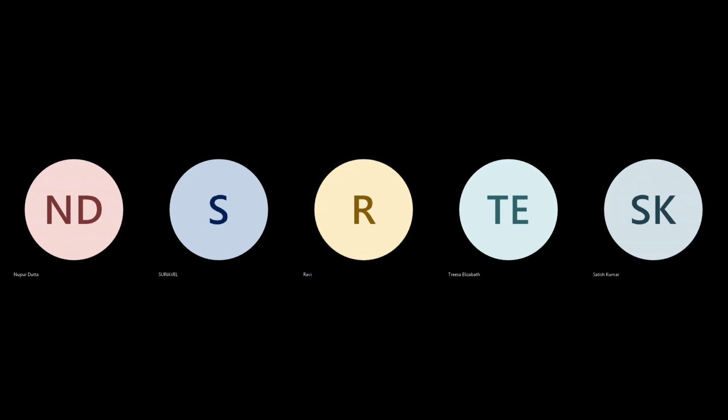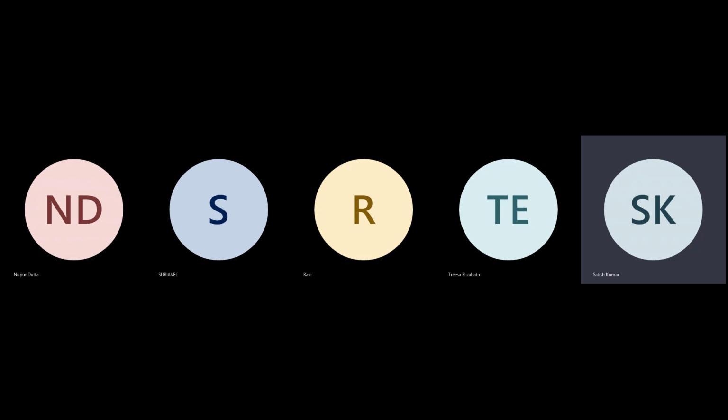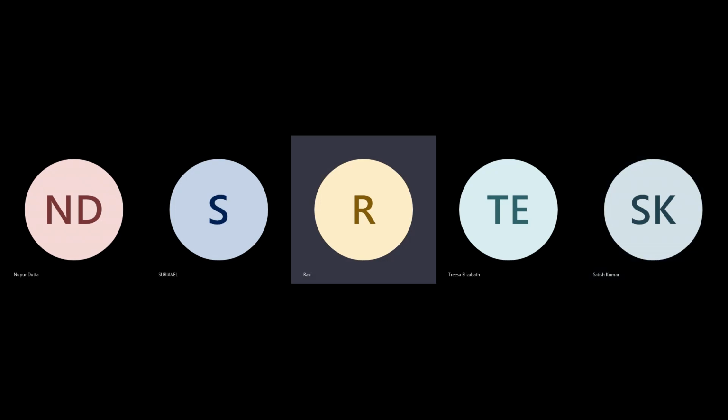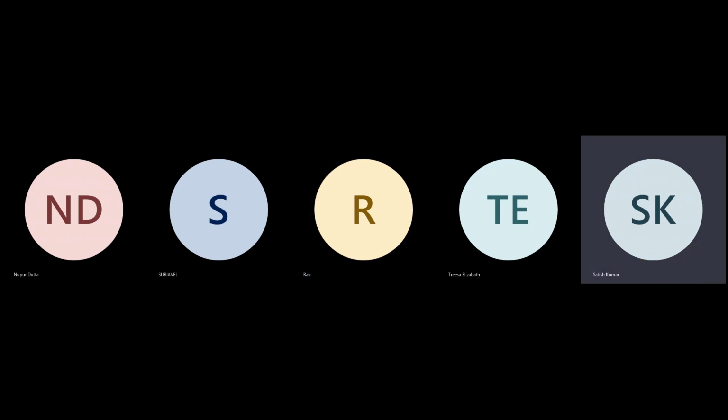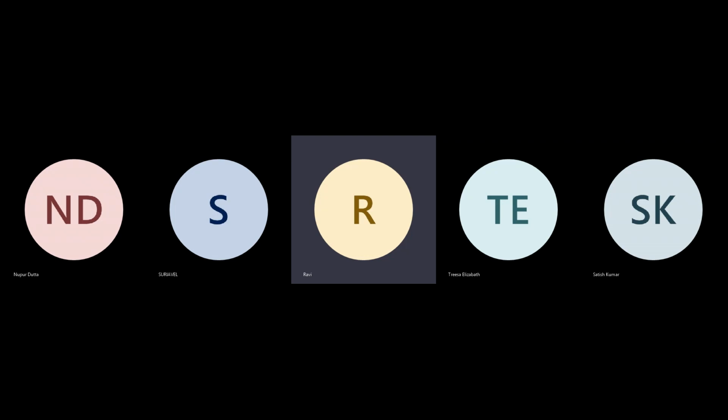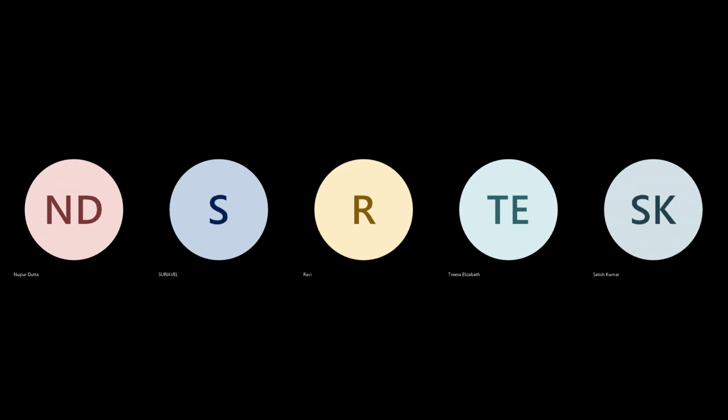Sir, Sridhar is asking what the steps in place are, what it will do. See, in place, what it will do is initial placement, as I said, right, coarse placement. Actually, first it will do coarse placement. You have to understand the sequence. Coarse placement is step number one. Then the second thing it will do is high fanout net synthesis. That's the next step.